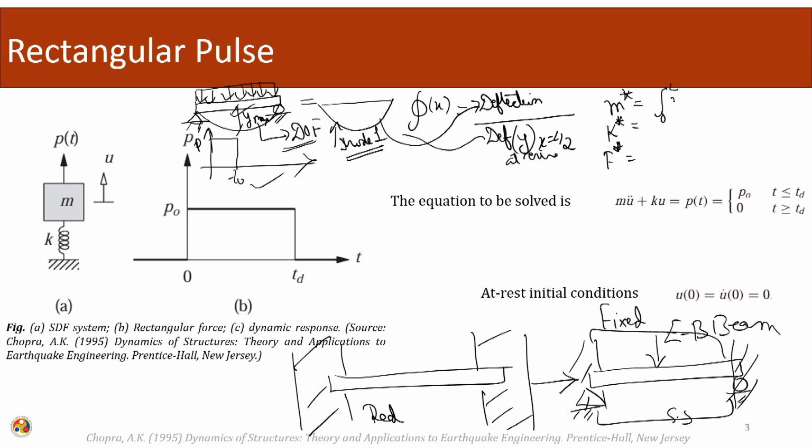So, 0 to L integrated, mass per unit length, stiffness again evaluated over the entire length, and the forcing function. In this way we formulate our equivalent mass, equivalent stiffness, and equivalent forcing function.